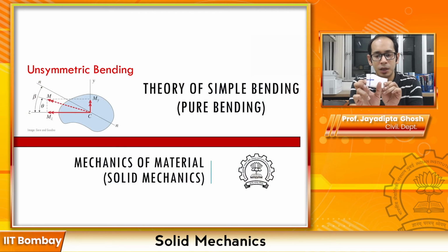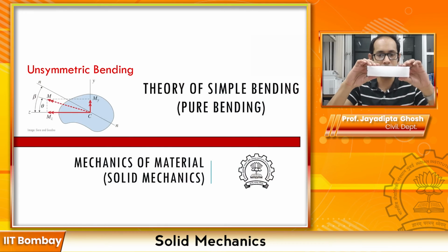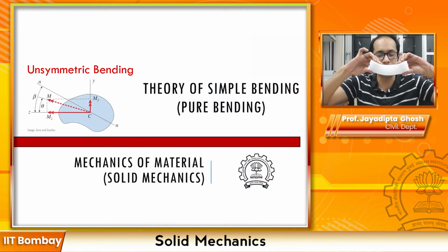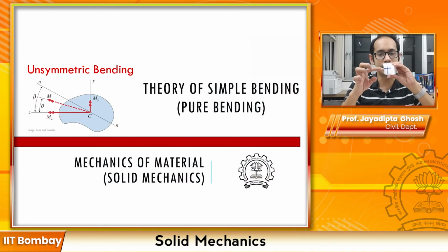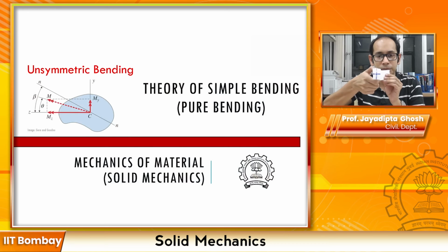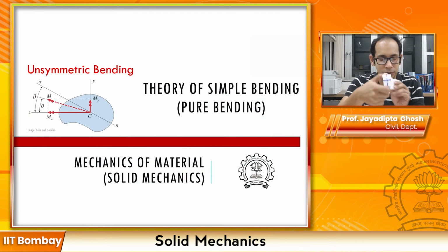So now if the beam, instead of how we are traditionally used to seeing it bending like this, where you calculate sigma x equals My by IZZ, was bending like this, so if you're looking from the top, it's like this, then in that case your sigma x becomes M divided by IYY, because it is bending about this axis over here.